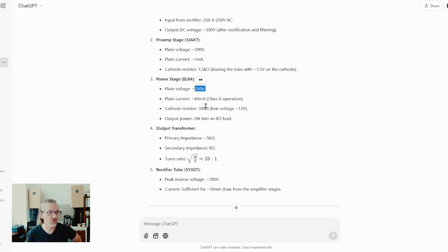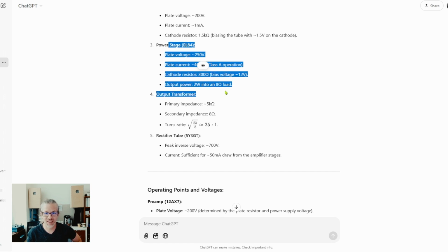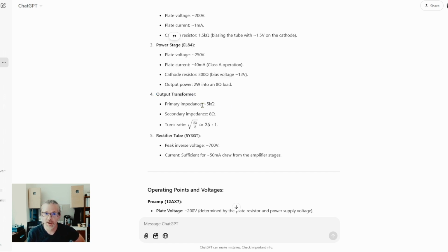Run the tube a little cooler, and then it will love it. And probably if we adjust this to maybe like 600 ohms or so, then it will bias to something like that. That's just a vague approximation. It will kind of work, but with this setting so far, you will just manage to cook your power tube like the Thanksgiving Day overbaked turkey.